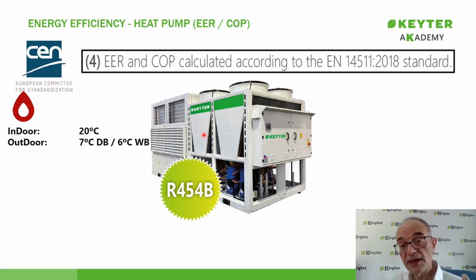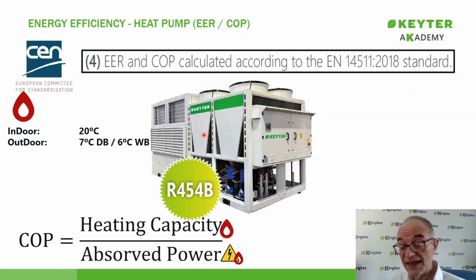We have the unit operate for a certain amount of time under those indoor and outdoor conditions, and the COP is the same as the EER, but now in heating mode: the heating power delivered by the heat pump divided by its final energy consumption. That's important for when we get into the concept of ETA. Right now, EER, COP, and the COP for process chillers will always be based on final energy.